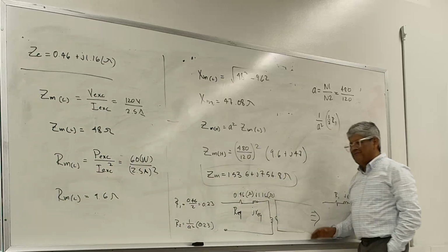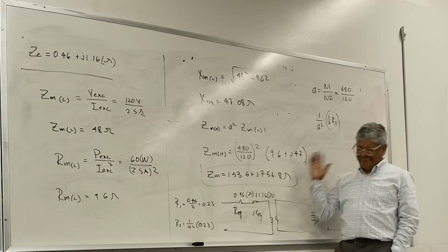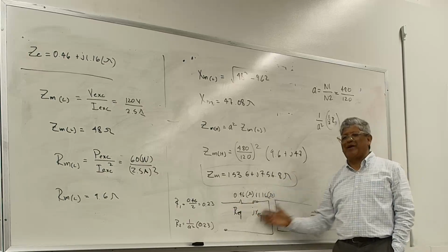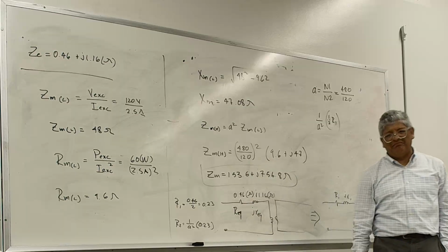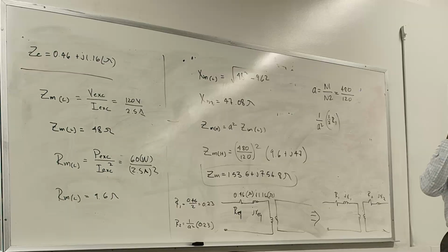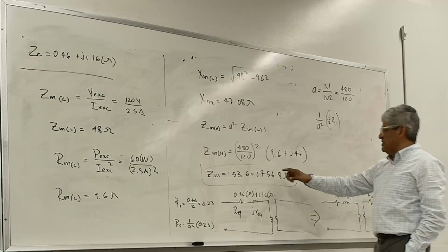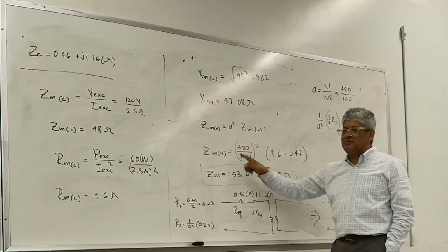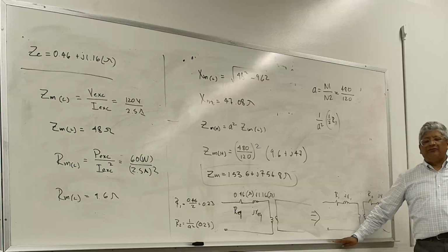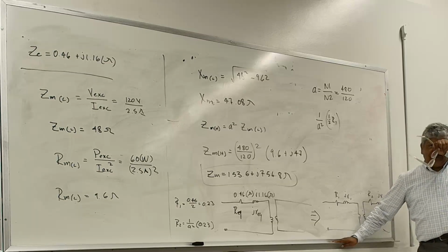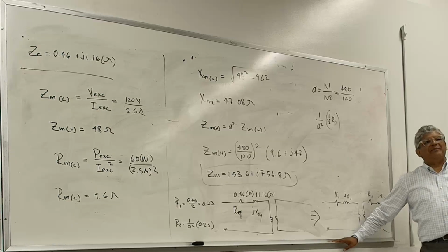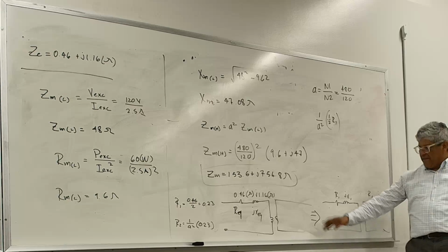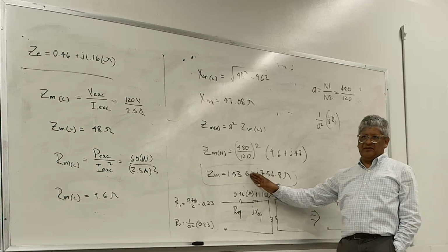For the most part, transformer models are going to be on the primary side, and the excitation branch will be here. But as I said, we're going to ignore it. Let me say this because I don't want you to think this is not important. It is important, but when? If you're energizing transformers after they have been de-energized for some time, this branch becomes critical.